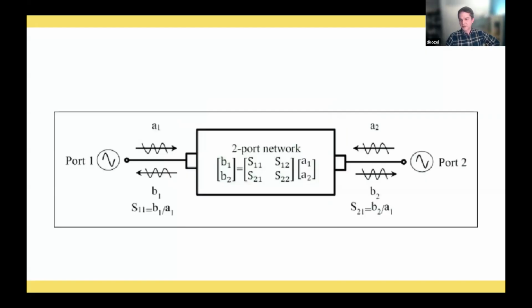What does that look like a bit more complicated? Well, we've got port 1, which has an A wave traveling into my filter. What other boxes have I got around here? Some little block filter or resistor or attenuator. Got plenty of those around, where we have 2-port devices. So we have power traveling into it. Some amount of it's going to reflect back.